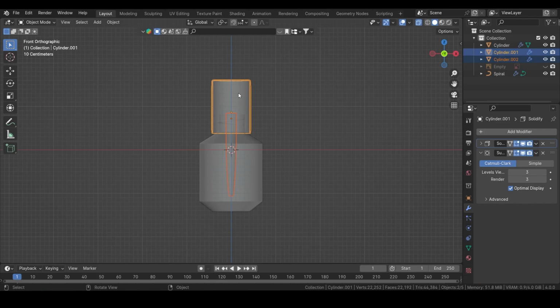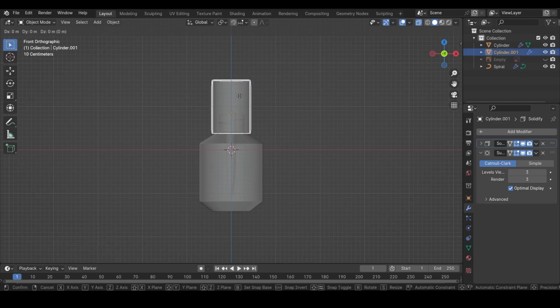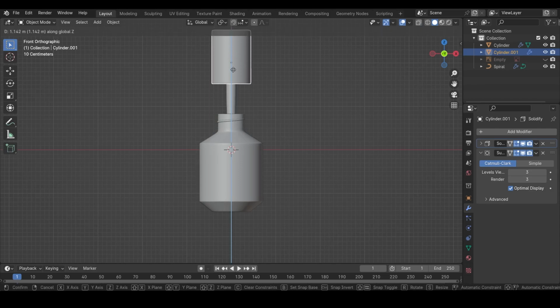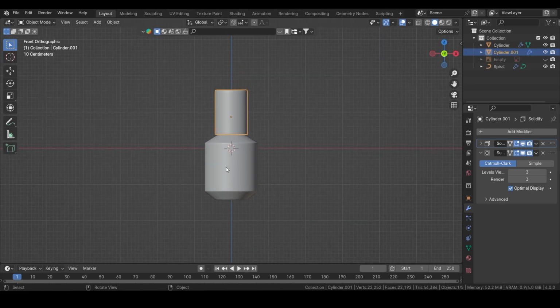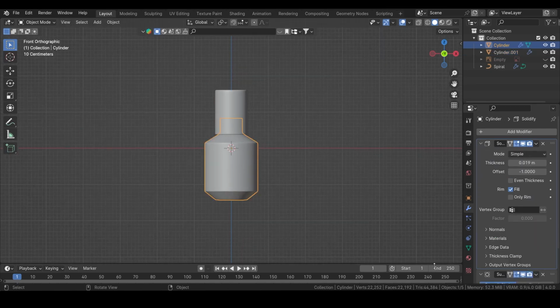You can parent the cover to the serum. Select the serum thing, then the cover, Ctrl P, and Object (Keep Transform). So when you grab this, it also comes along with the serum. So now the next thing is the label.